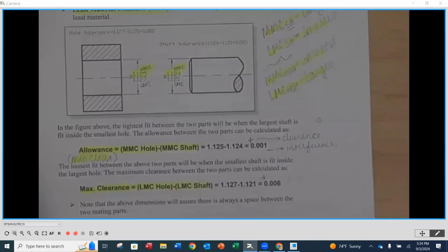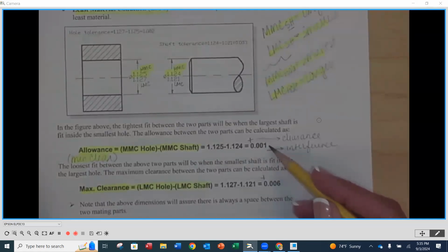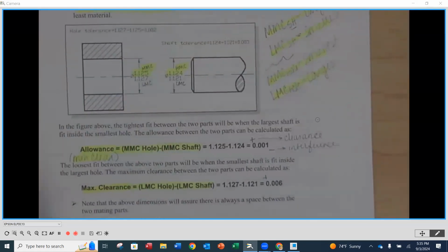1,000ths, 6,000ths. They're still kind of tight, especially the 1,000ths. This one starts to get into a moderate tolerance, I think. Like you do this on a Bridgeport, I like to think of it. But this guy, you're putting it across something, maybe more than one something, to achieve that. So I want you to think in those terms and be able to identify small tolerances and large tolerances, because the smaller the tolerance, what happens to the cost of that part?